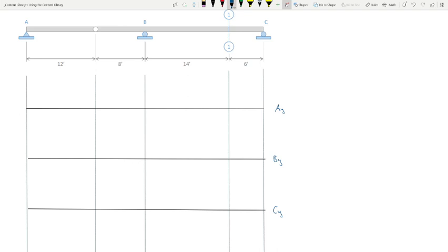All right? We remove from the structure the ability to resist the reaction at A. So if I have this reaction at A and I pull a this is Sparta and I just kick it out, okay? What does the beam look like? It's a beam, it's got this segment, and then there's this hinge right here. So what does the beam do with this roller or this support gone? What does it do? What falls down?